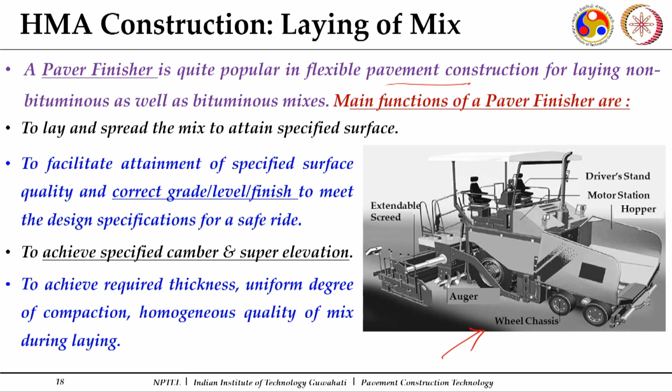The main functions of a paver finisher, the specific functions because of which they are preferred, are to lay and spread the mix to attain the specified surface. This also needs to take care of the surface quality, correct grade, level, and finish to meet the design specifications. Because these are my upper bituminous layers, they have to be properly laid with good control of the surface levels and surface regularity, and that is done in a safe mode.